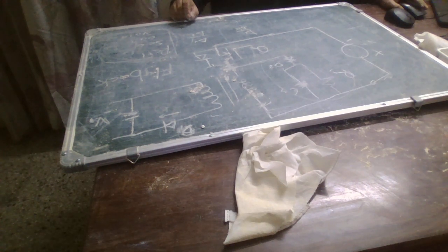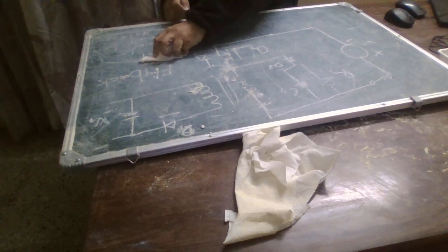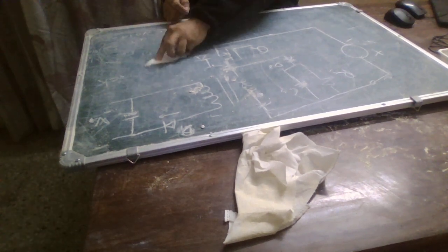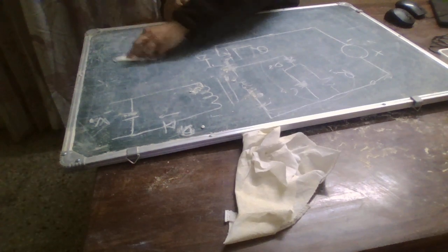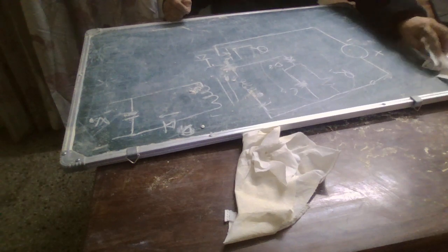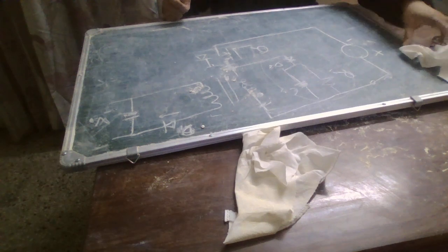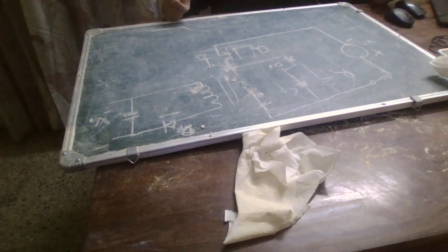So what would be the meaning of the continuous conduction mode in this flyback converter when we are using transformer isolation? We know that continuous conduction mode means the inductor current never reaches zero, and when we are talking about the continuous conduction mode in the flyback transformer, we are talking basically of an incomplete demagnetization of the transformer core.